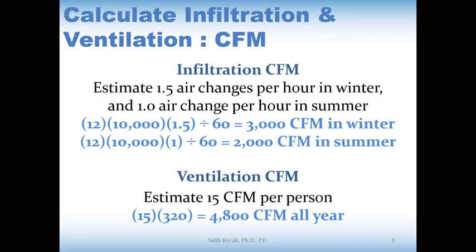Previously, the conservative designers were still adding them up. However, please do not forget that ventilation fans pressurize the building, so they overcome the anticipated infiltration. That's why most of the time, in your calculations of infiltration and ventilation, you will see that ventilation is going to be larger than the infiltration.